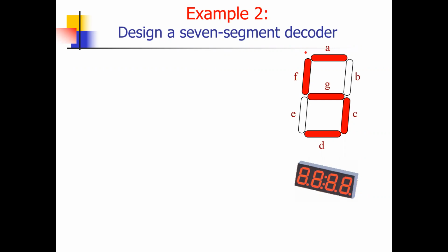Look, if you want to represent in traffic signal 0011, you know it's 3. The normal person can understand? No. That's why you need this 7 segment. 7 segment will represent the decimal numbers 3, 2. So anyone can read this number. That's why. But now the question is, how can I convert? Using the combinational circuit. We will design it. Okay. So how we can design?